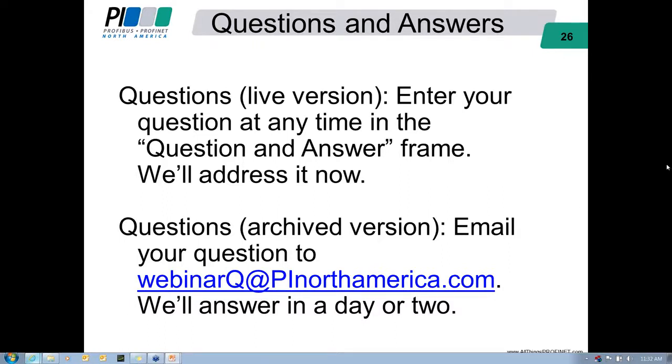Okay, let's see. I manufacture PROFINET devices. How do I add PROFIenergy? There are a number of ways to do that. Recently I saw a product announcement from the company HMS that does the Anybus modules. Those modules are often used by manufacturers to add PROFINET and many other buses to products. They introduced their PROFINET version that already includes the PROFIenergy application profile built in, and I'm sure many of the other development tool suppliers will do that as well. So really a straightforward addition if you're manufacturing PROFINET devices.